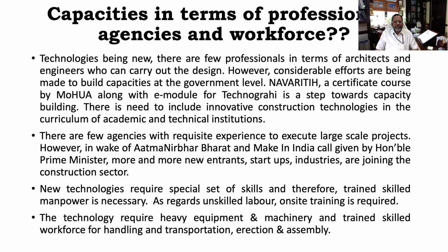Because this technology has already become mainstream, there are a number of agencies who supply this formwork, and now even regular contractors can undertake the work using these formwork systems. So requisite experience to execute larger scale projects is now available. However, you need to seek help of the technology provider or the formwork manufacturer who will guide you about the formwork installation and its removal, and installing it on other floors.